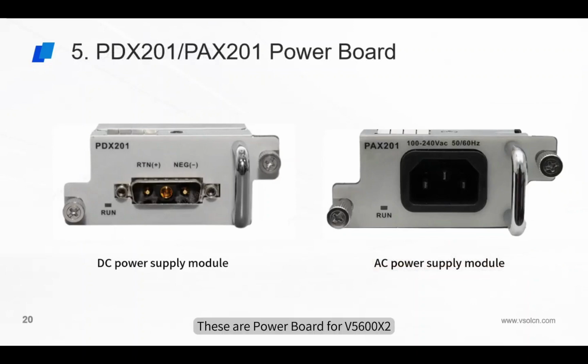These are power boards for V5600X2. PDX201 power board is a DC power supply module. Requires connection to a -48 volts power supply. PAX201 power board is the AC power supply module. Requires connection to an AC 220 volts 50 or 60 Hz power supply. The available slot to connect power board are slot 3 to 4. It also supports dual power redundancy backup.